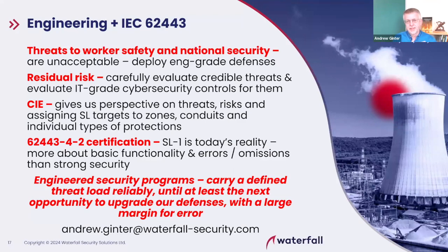I'm an old man. I'm a grandfather as of a week ago. The young folk today are using the term air gap to mean cannot route a packet from this network to the internet. That means the network is air gapped. It might still have a firewall. The OT network might have a firewall to the IT network, which has a firewall to the internet. If the IT/OT firewall says no packets can go from the OT network to the internet, it has denied by default, they call it an air gap.